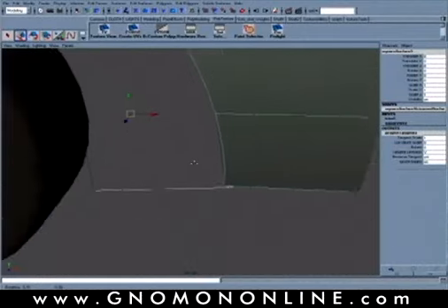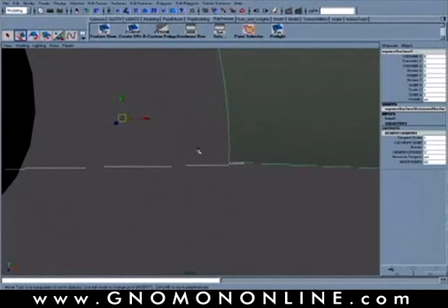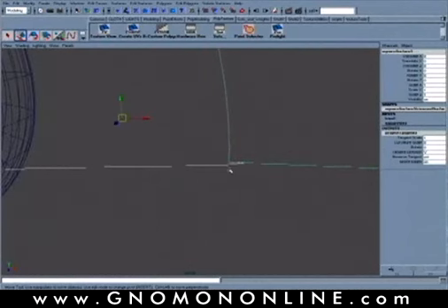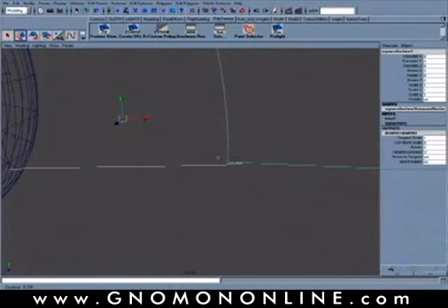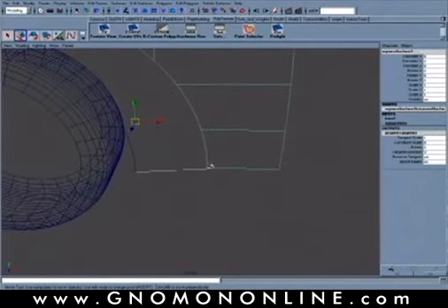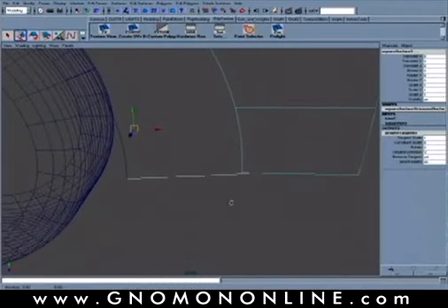Okay, so now that is aligned or running along the V direction. If we look really, really close, though, we can see that there's actually a little hook on the end. Okay, this surface is doubling back here. That slight little hook just means that the tangency is trying to create it going in this direction to the left instead of smoothly integrating to the right here. So you can fix that a couple ways.